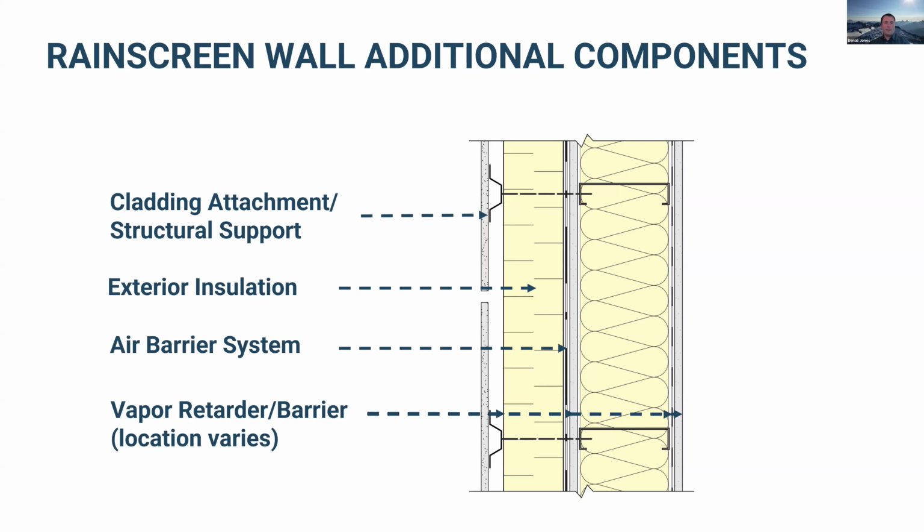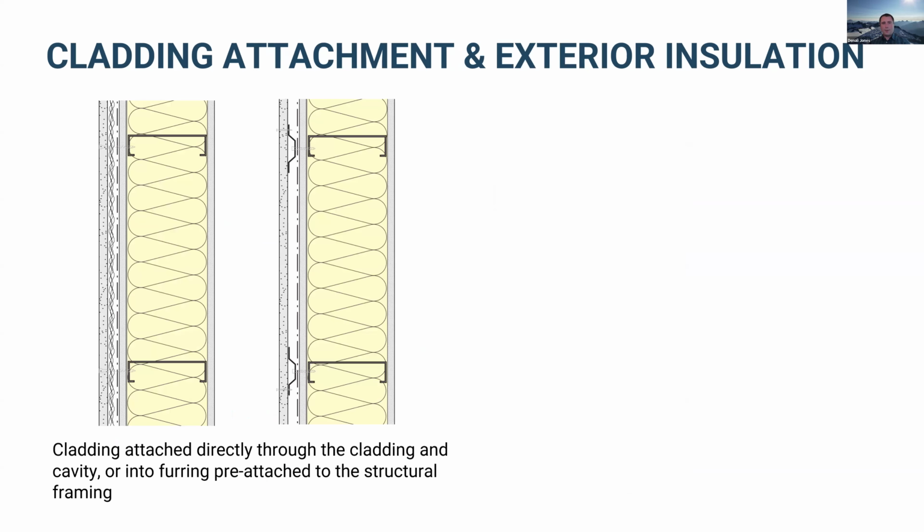going on here. So for the skinnier walls where cladding is attached basically through the rain screen cavity directly, just using long screws that go back to studs, that's a bit simpler. So this is showing hat channels or just a drainage mesh here. That can work well.